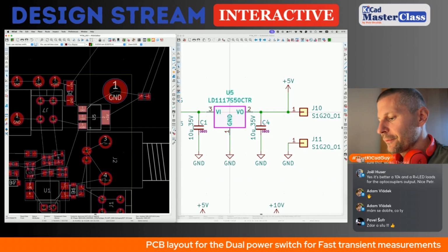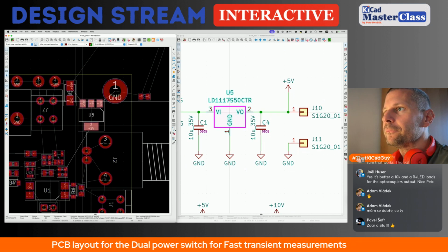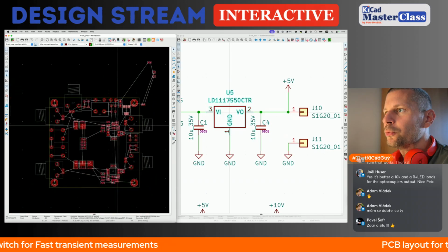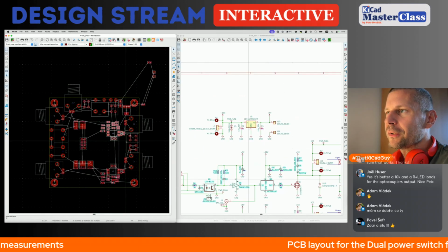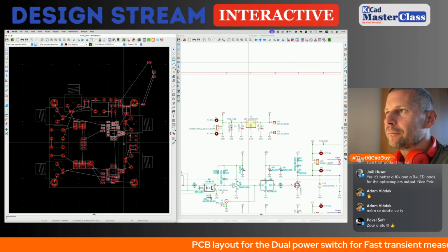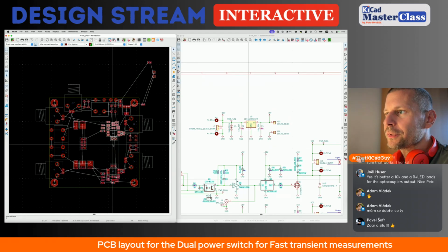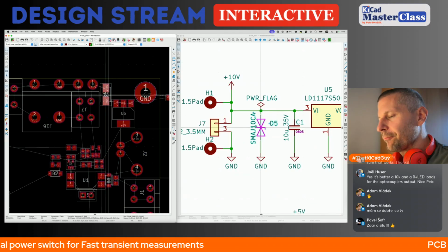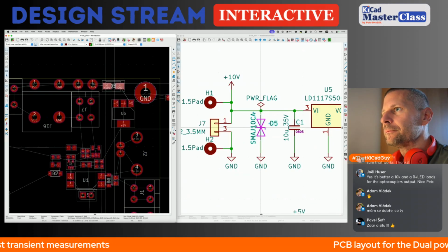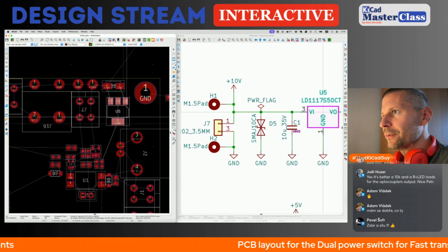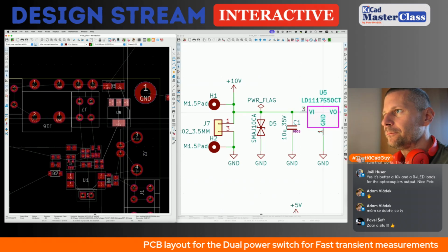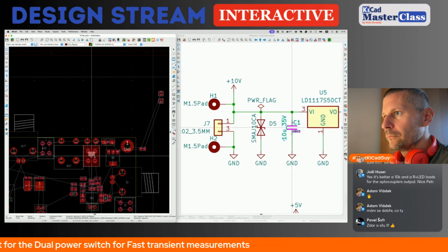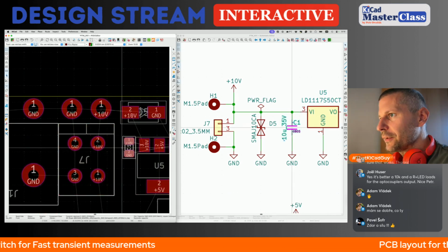So where to place the LDO? We have two possibilities. Here, I can move the logic circuit a little bit downwards. I can place the TVS here and use this area for the LDO, with its decoupling capacitor near the pin 3.